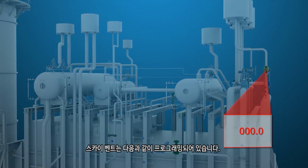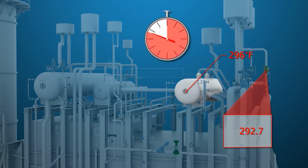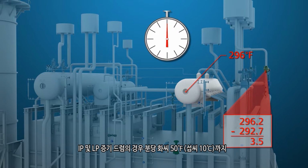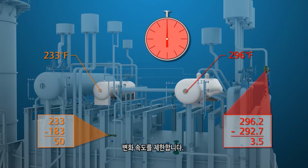Sky vent logic is programmed to observe the temperature change in the associated steam drum and limit the rate of change anywhere from 3.5 degrees Fahrenheit per minute in high-pressure steam to 50 degrees Fahrenheit per minute in the IP and LP steam drums.